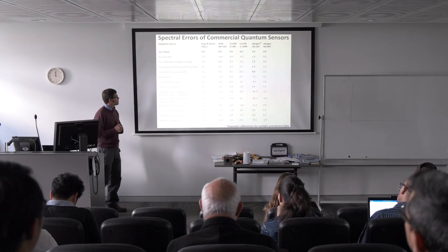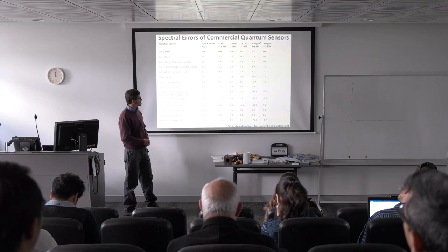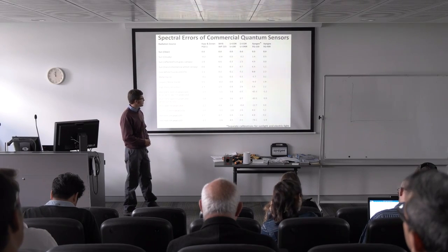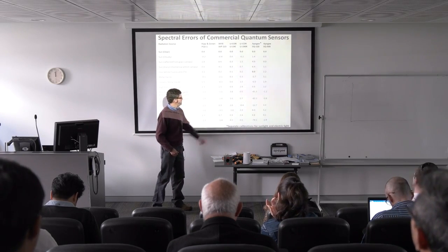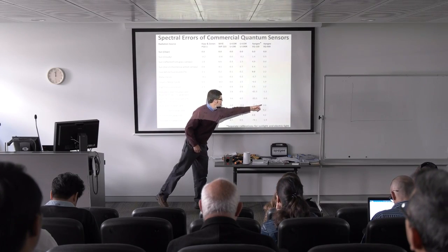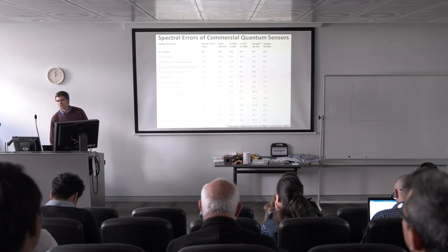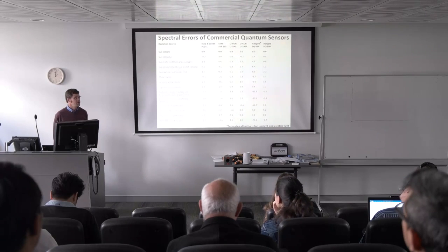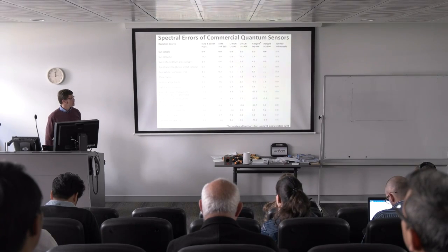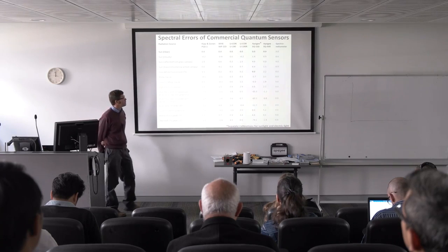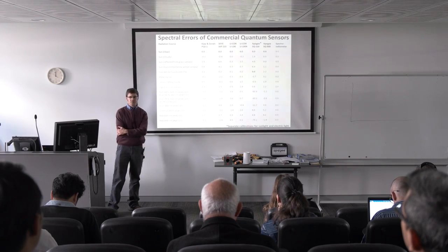You'll notice of the other sensors, some of the worst errors also tend to be LEDs, right? So here's a 3.8 and 3.6%. That's an LED. A 3% over there, that's an LED. LEDs are tricky to measure, so for those of you that are working in greenhouses and measuring LEDs, sometimes the best option for that might be a spectroradiometer.